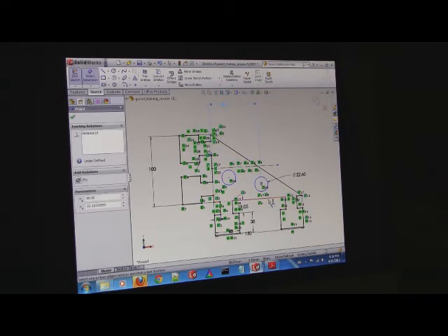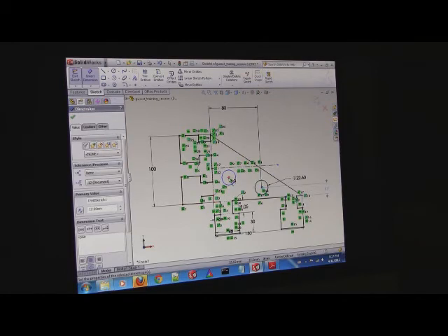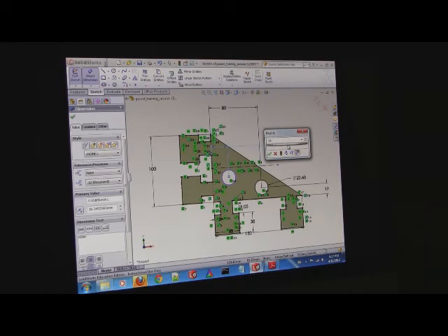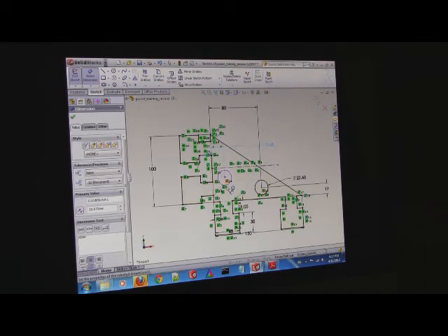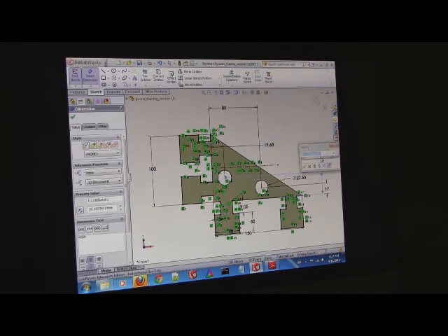The bottom right hand one is dimensioned as 80 from the left hand side. It's dimensioned as 17 from the bottom. And then this left hand one is 19.675 from the left. And then it is 28.25 from the bottom.